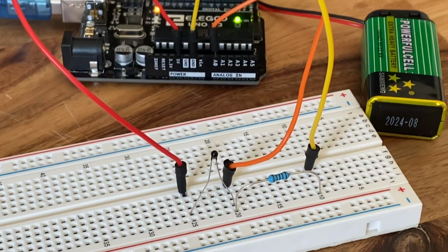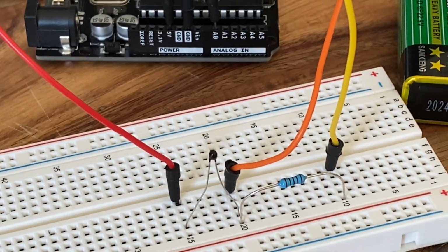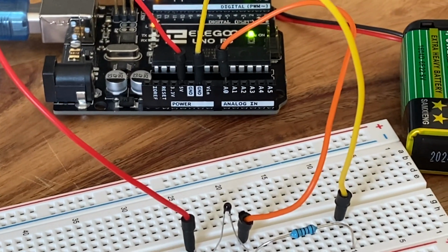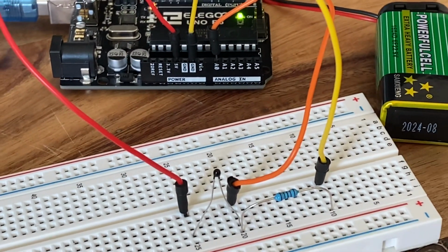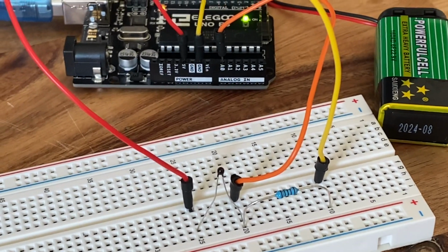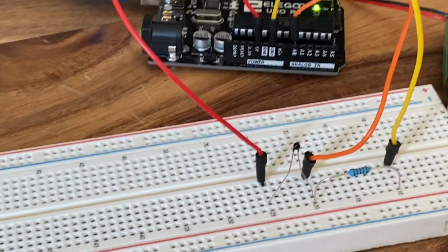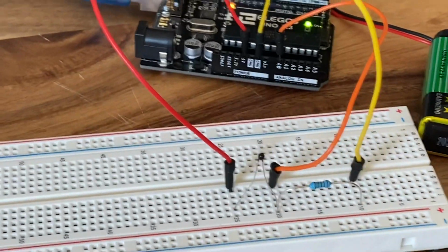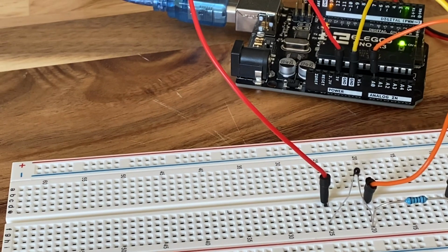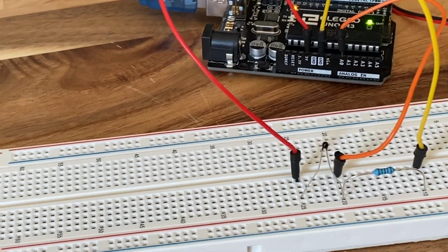What I needed to do was write some code to convert the voltage that we're reading from this orange wire and the A0 analog input into temperature. You can accomplish that by using the Steinhart-Hart equation and calibrating a couple of values, which eventually outputs the temperature in Celsius and/or Fahrenheit. So that's basically the circuit.